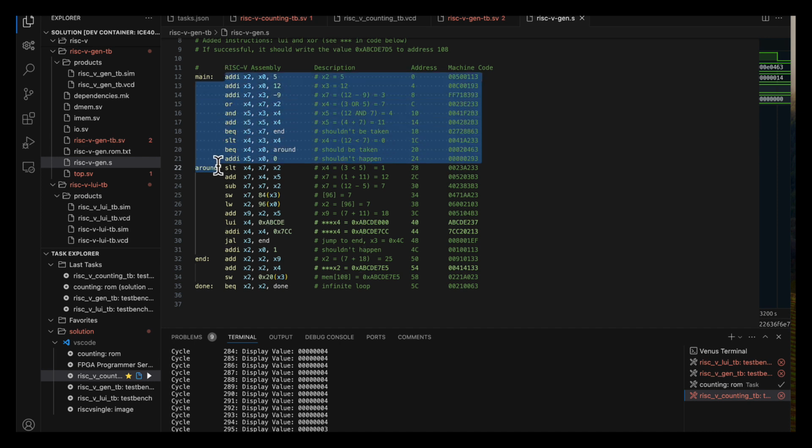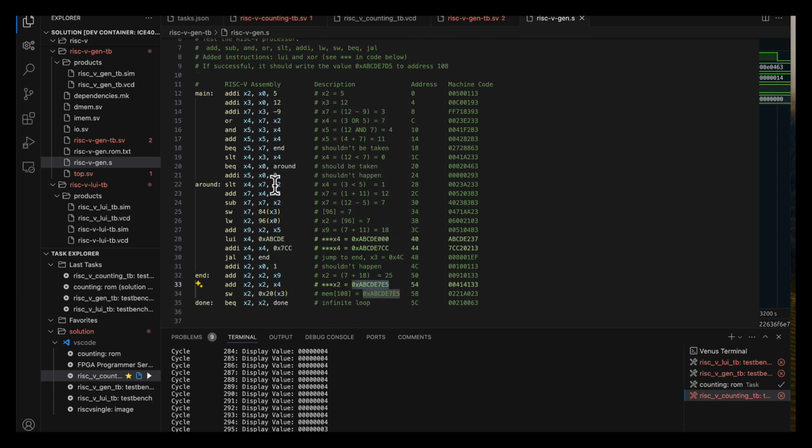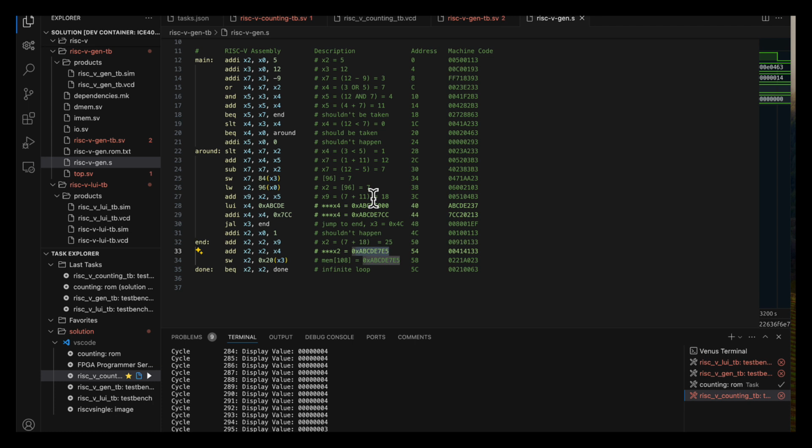And basically each of these contributes to a calculation. And at the end, if they've all worked correctly, we get a known predictable value. If any of these end up failing, that final value will not be the correct value or will be uninitialized. So if something goes wrong with this, you may have to think through it step by step and check in at each step and look to see whether registers are being updated with the appropriate values.